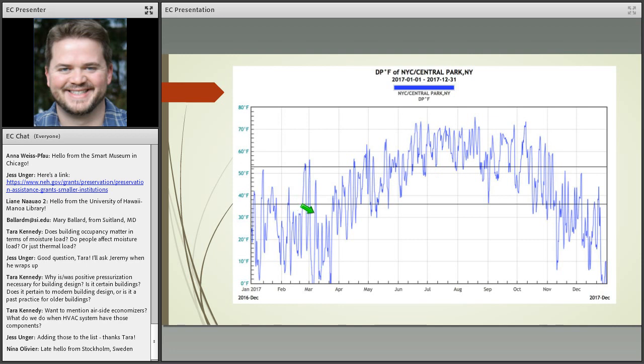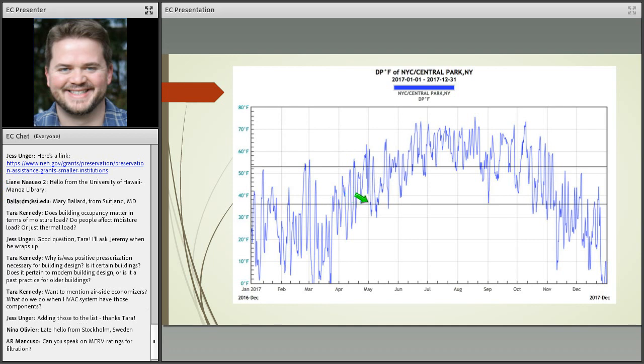But especially notice here on the lower end that if we start to think about the ability in the wintertime to use a seasonal set point of 65 degrees and 35% relative humidity, notice that when we get to that 36 or 37-degree dew point, this is my control point. This is all the higher I need to bring the moisture content when I'm humidifying. So it's all this time underneath.